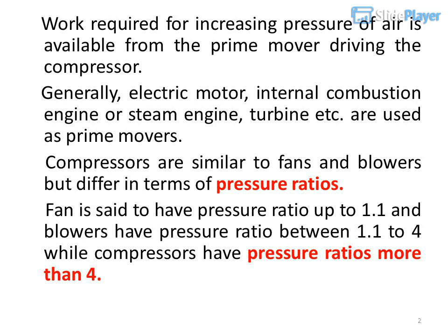Compressors are similar to fans and blowers but differ in terms of pressure ratios. A fan is said to have a pressure ratio up to 1.1, blowers have a pressure ratio between 1.1 and 4, while compressors have pressure ratios more than 4.